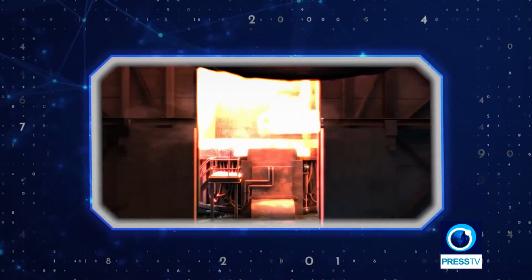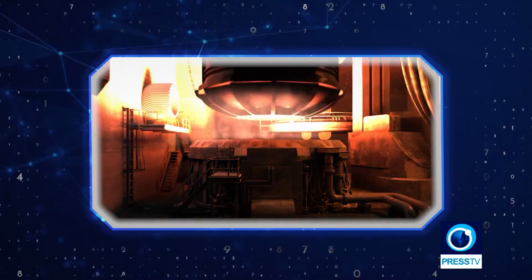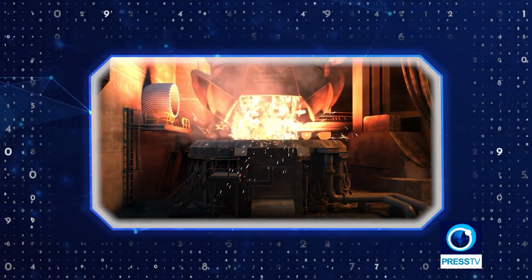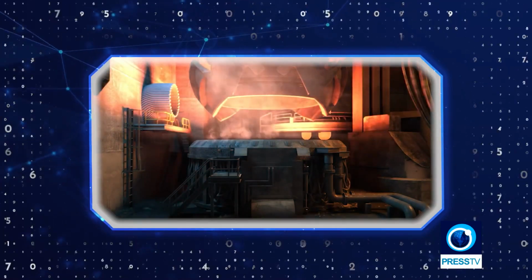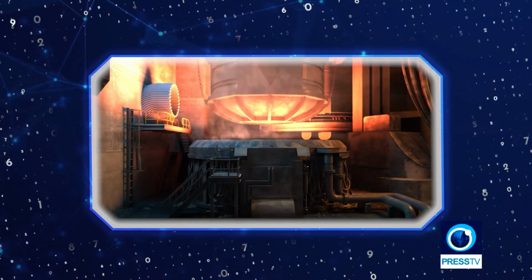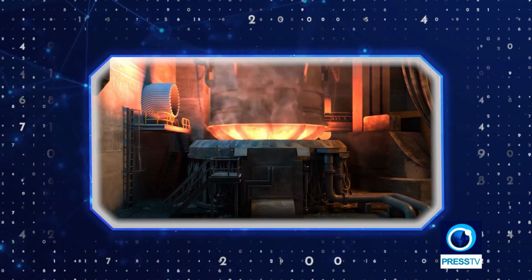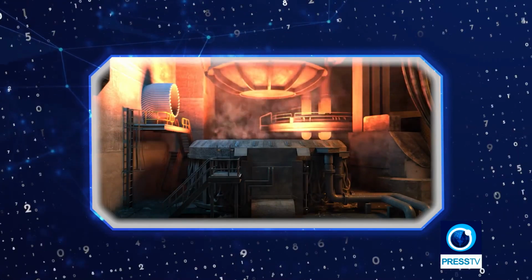Here, the steelmaking process relies on electric arc furnaces, EAF, which allows for greater energy efficiency and easier control over the raw material mix compared to traditional blast furnaces. It starts with sponge iron and scrap, melted at extreme temperatures. This is where the base of the steel is born.